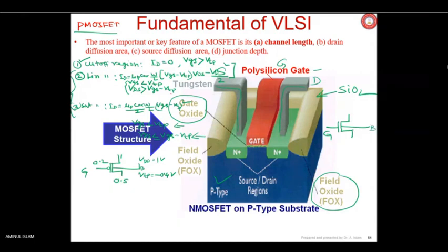But out of the remaining two terminals, top and bottom, which one is what? It is a symmetrical device. Remember that structure is in front of you. It is totally symmetrical. There is no preference for which one you will call drain and which one source. But you have to remember that in the case of N MOSFET, the node at higher potential is the drain, and the other one is source. You're getting my point?